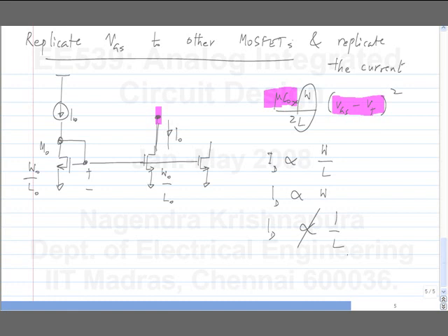For instance, if we had transistors in velocity saturation, what's the current? What is the current expression in velocity saturation? I think that's what it is. Is there a divided by 2? I think, yeah. So in this case also, clearly here the current is not dependent on L at all, right? Whereas it is directly proportional to W.